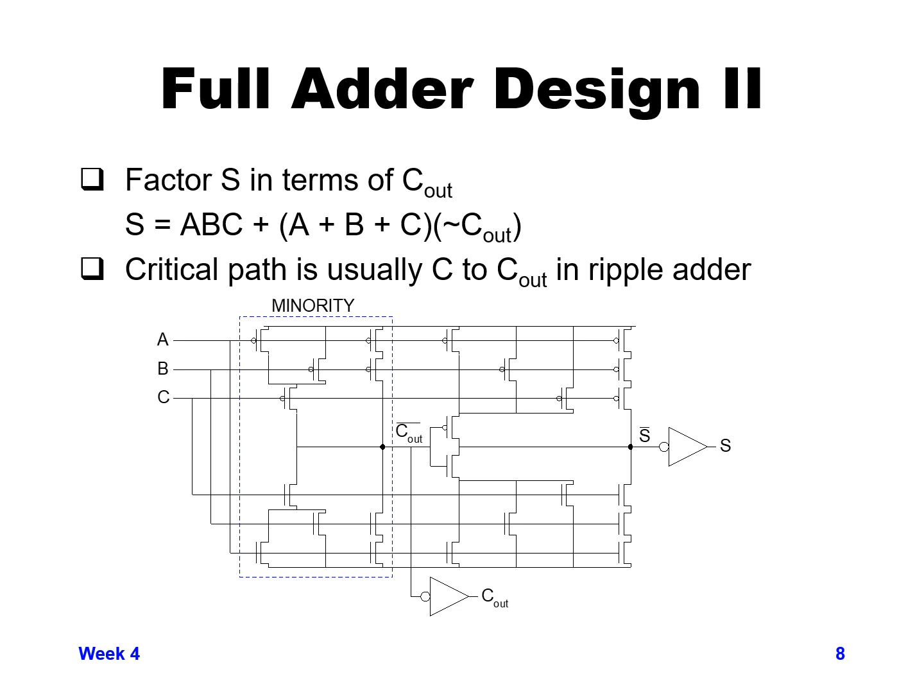Also, if you look at this particular design, since we only need A, B, and C, we don't need the inverted versions coming in. The total number of transistors needed for this design add up to 28 transistors, as opposed to the 32 that were in the design that we had for the adder design 1.